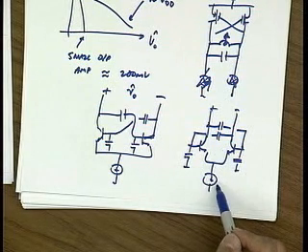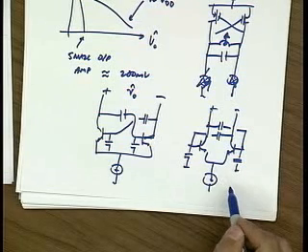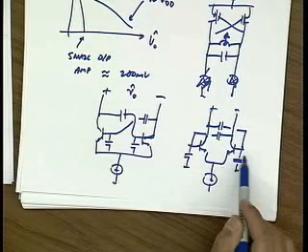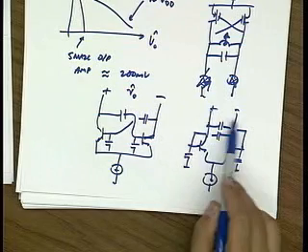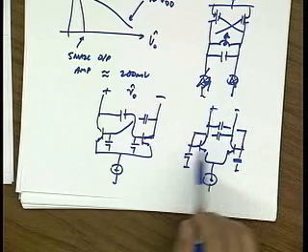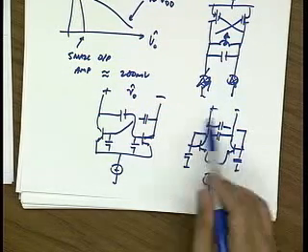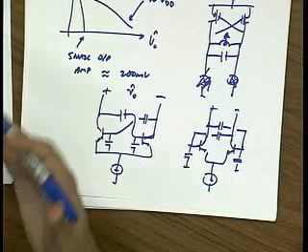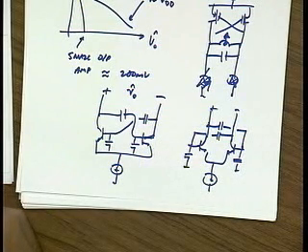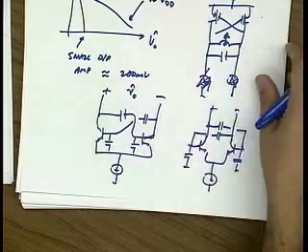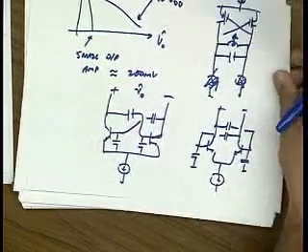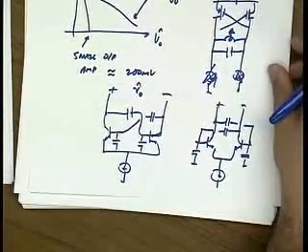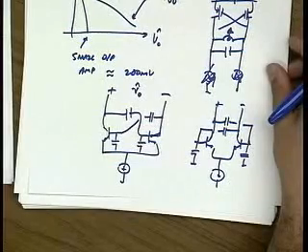And so then you can see that the noise at different harmonics of basically the switching frequency can fold into band due to the switching mixing action. So the noise of this circuit is also complicated, just like the noise of a mixer is complicated. All right, just to get you guys thinking a little bit ahead. Okay, good questions, guys. Any others?